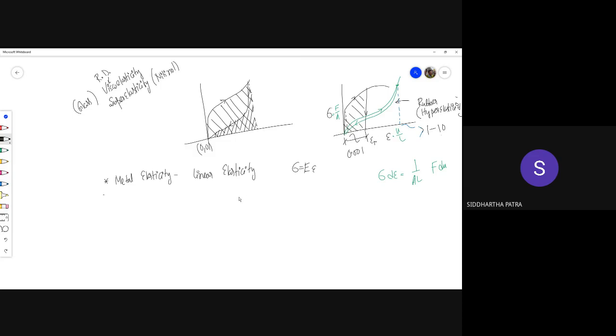Now we would talk about the multi-axial forms later, but you need to understand this linear elasticity of metal is only valid in this tiny, tiny domain of strain. So what we do, typically in most of the problems that you solved in your undergrad, is try to keep the maximum stress in your system below a certain working stress, and that working stress would be yield stress divided by some factor of safety.